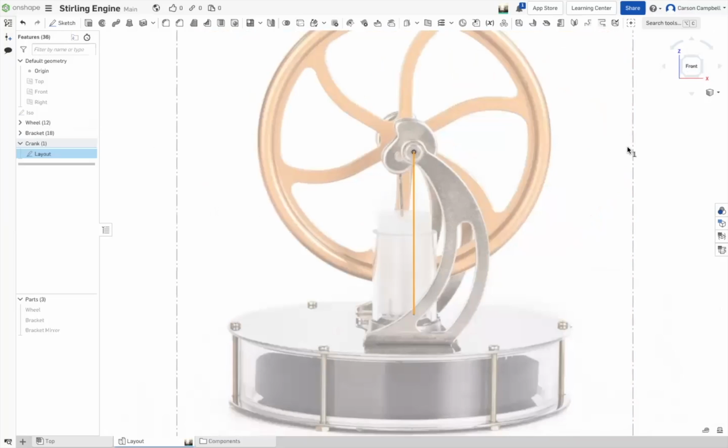So we're going to have a bracket, a wheel, and a shaft. All 3 of those are going to be playing around with a 3mm shaft. So we need to make some decisions here. One, what's the diameter of the shaft? We're going to have the diameter of the shaft to be 3.